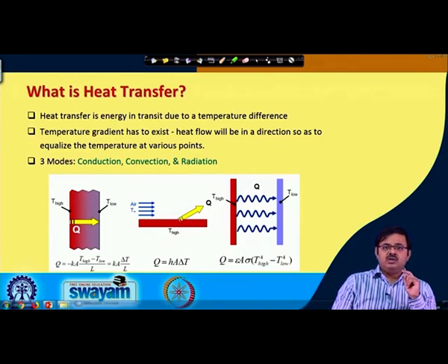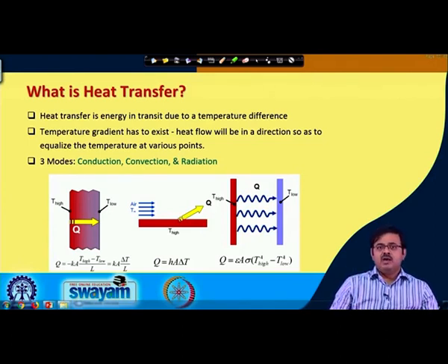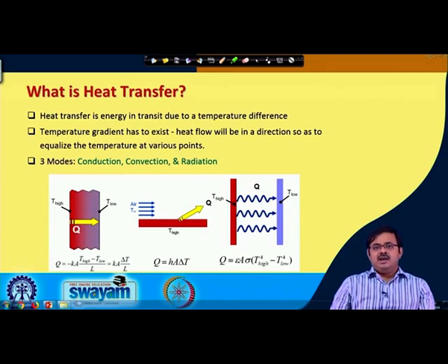Okay. So, the amount of heat that is emitted, apart from depending on the fourth power of its absolute temperature, also depends on the emissivity of the surface. Okay. And emissivity typically lies between 0 and 1. When the emissivity is 1, it is known as a black surface, sometimes also called a black body, but when we talk about radiation heat transfer, it is more about surface. So, we will call it black surface,